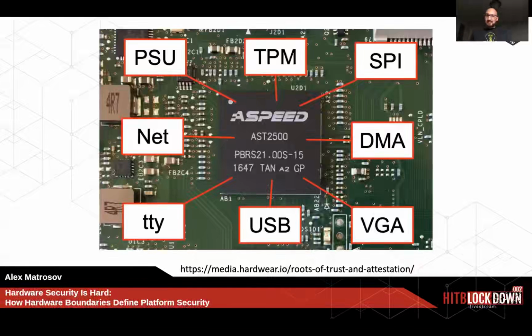Let's get back to the BMC. The BMC can update the firmware for most of the devices across the board. Even more, it can update the TPM and has infinite control over the SPI flash controller. It has a separate network interface, not dependent on the system board interface provided for the operating system and others. It's just separated for functional purposes.